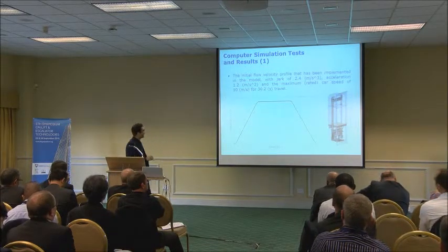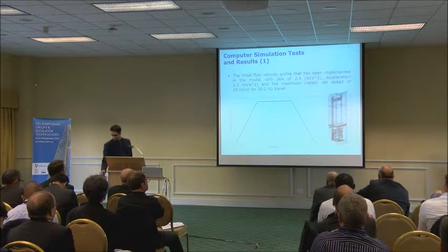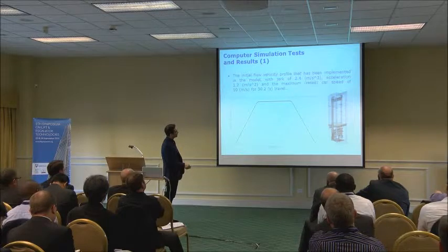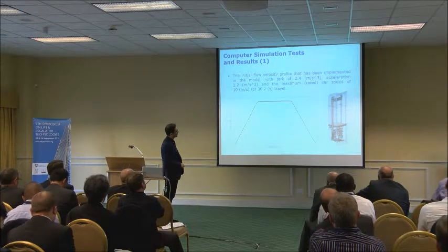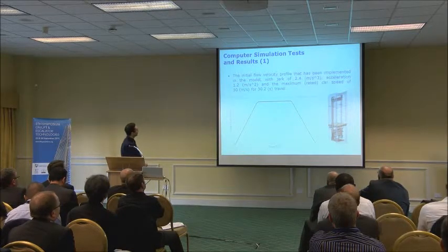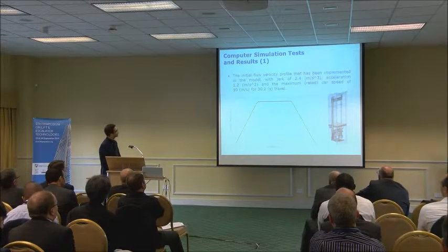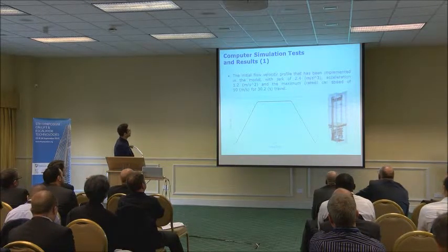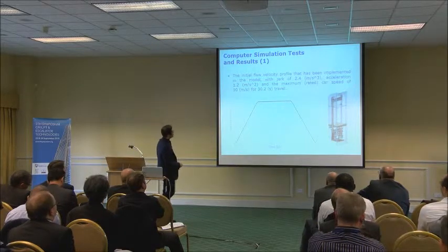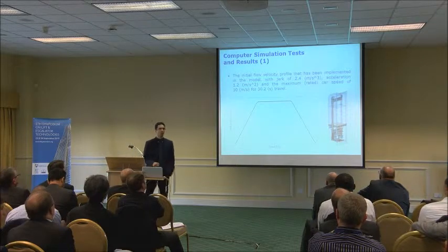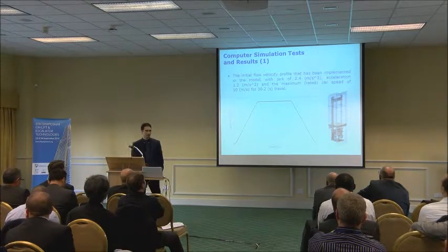If we want to start the actual model itself, we have the model of the elevator, which we will be importing through our CAD models. And we have the profile of the speed, with a jerk of 2.4 and an acceleration of 1.2 meters per second squared, and a maximum constant speed of 10 meters per second for an overall travel time of 30.2 seconds.